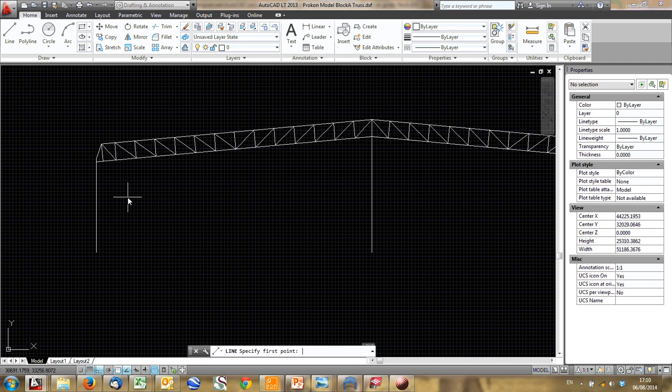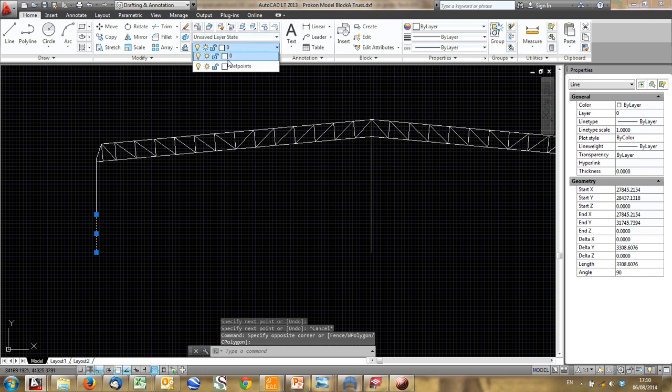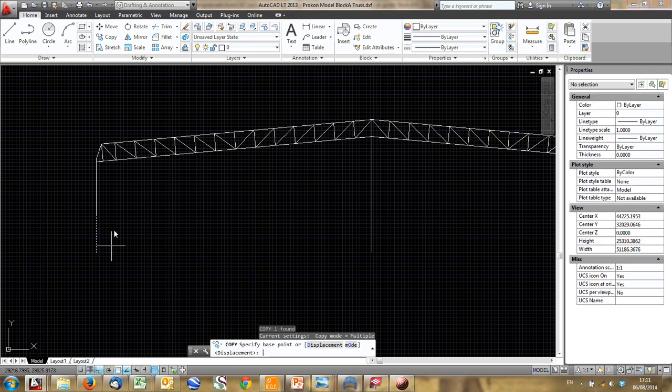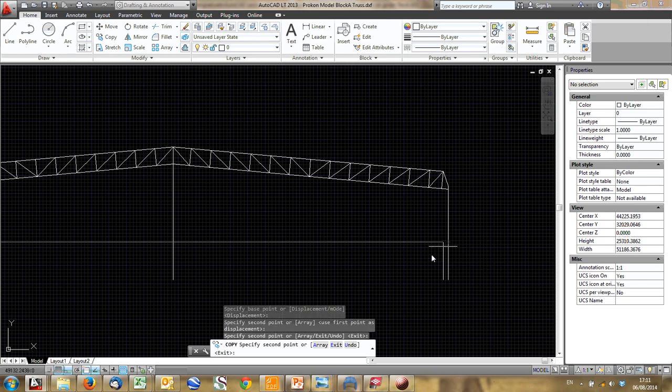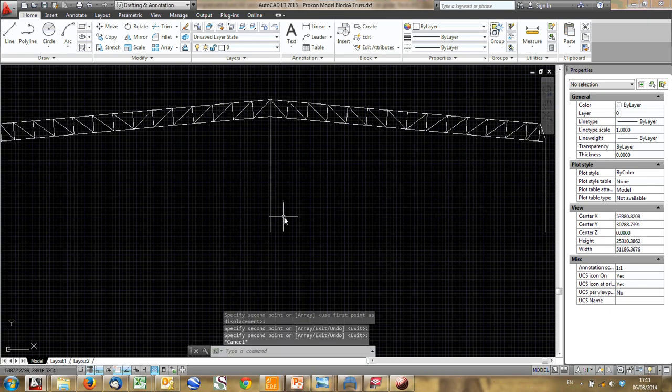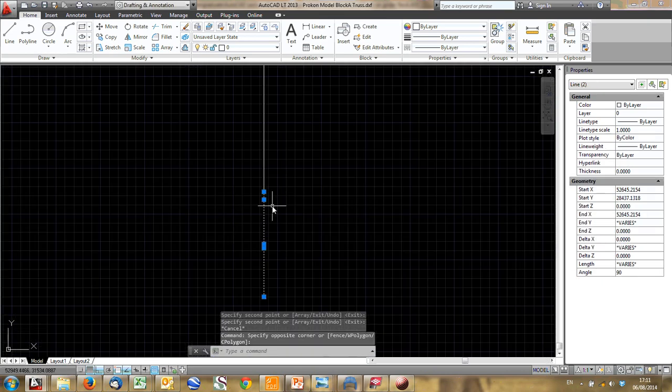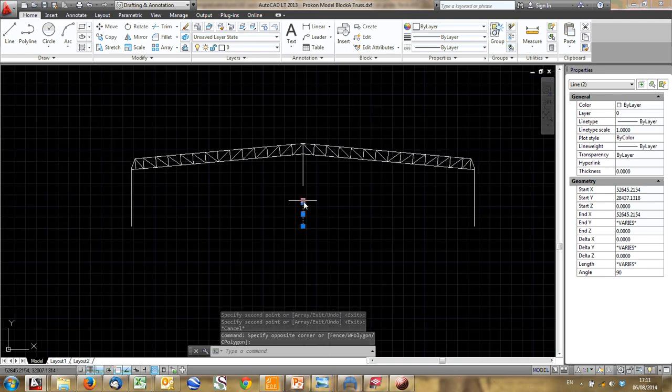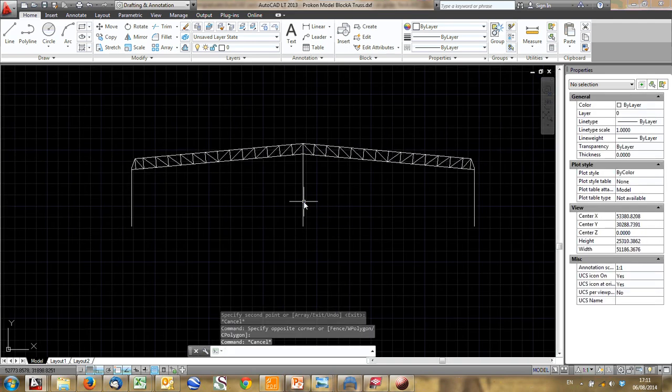Also, make sure wherever you need a node, let's say we've got our concrete column there, you have different lines wherever you need a node. So we'll add sections like that. They don't necessarily have to be different colors. Add it all the way along, so at least then you have a line stopping there, so you know it will create a node when this is imported into Prokon. So we can draw this out, save it, close it.